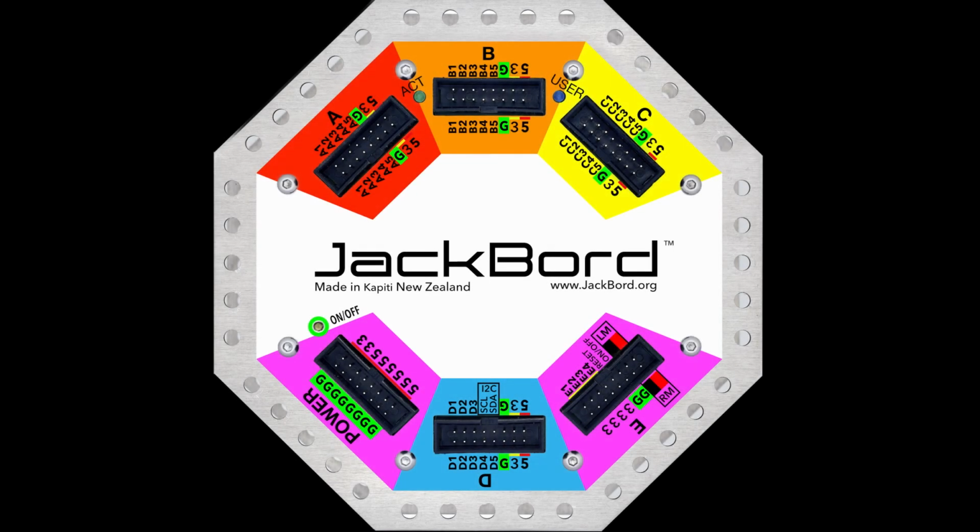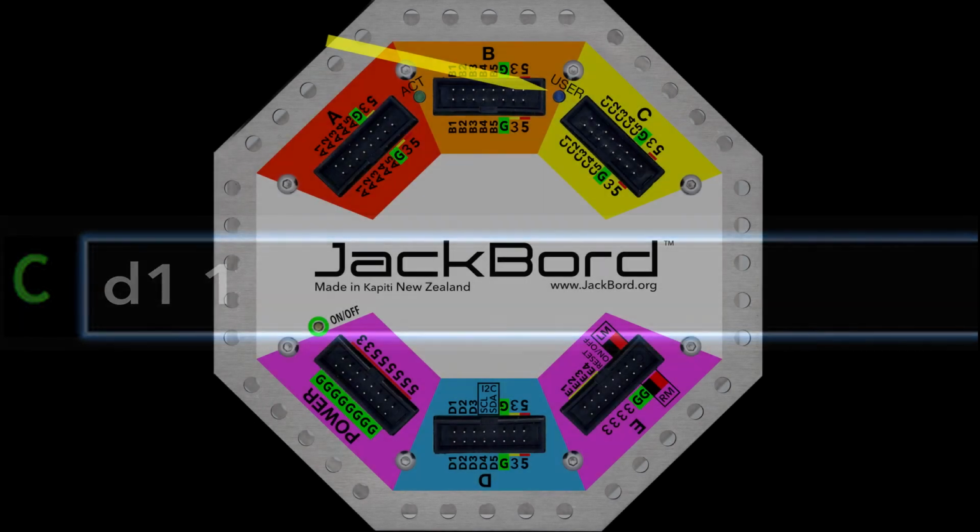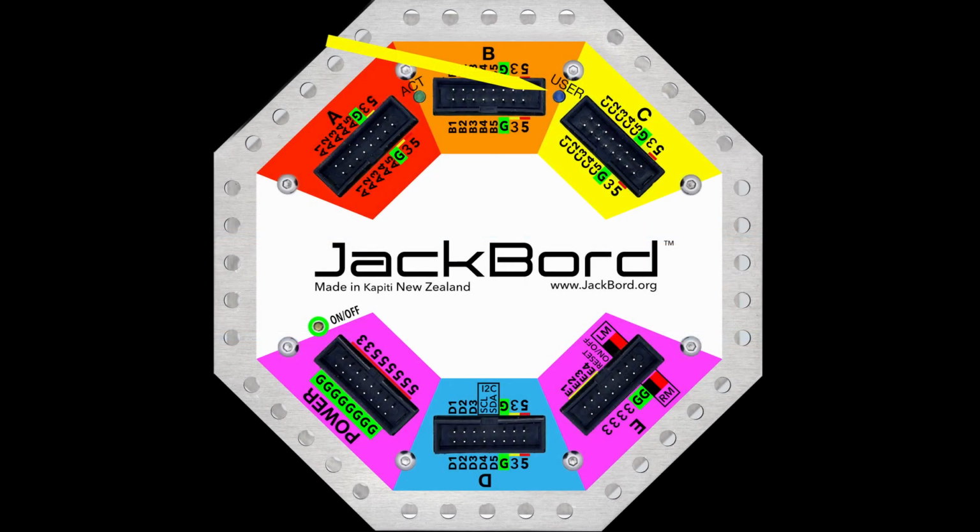Turning the user LED on and off. This next command will let you turn the user LED, which is located to the right of port B, on and off. The pin that controls the user LED is pin D1. So if we want to turn the pin on, the command is D1 space 1. Type this at the command prompt and press Enter. If all is well, you should see the blue user LED turn on.